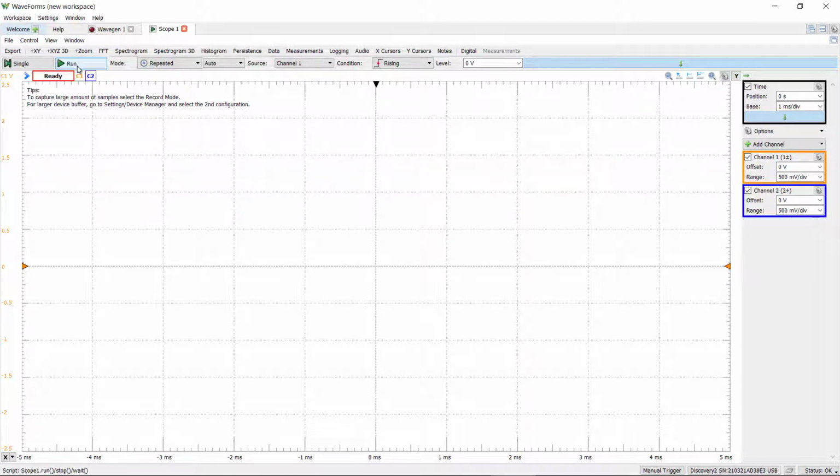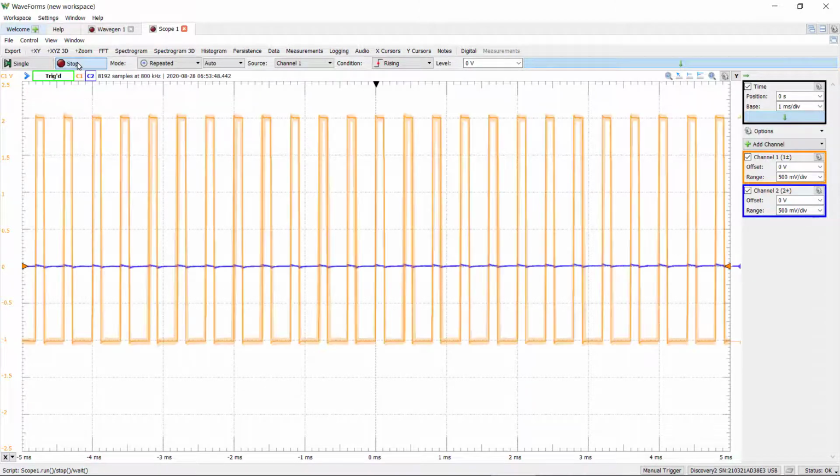What do we expect to see before we look? Hey, it's going to be roughly an offset square wave with some funny duty cycle. Let's take a look. We run and it's going to be about 2 kilohertz or so, 1.5 kilohertz. And here's that signal. It's distorted a little bit. I have channel 2 on. We're going to look at channel 2 in a little bit because we're going to look at the crosstalk on channel 2.